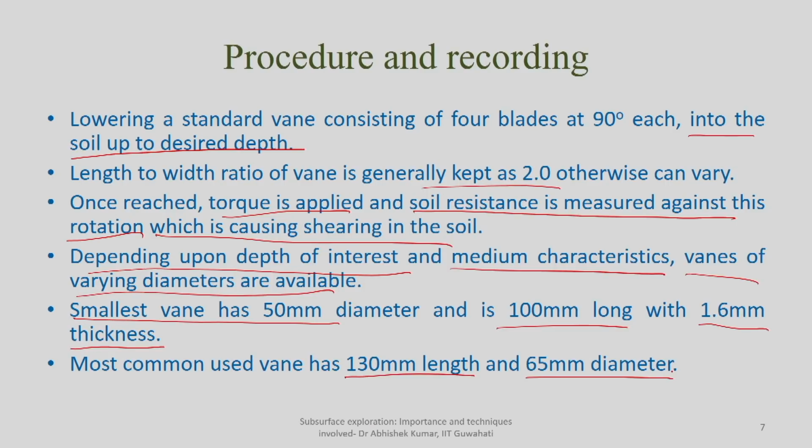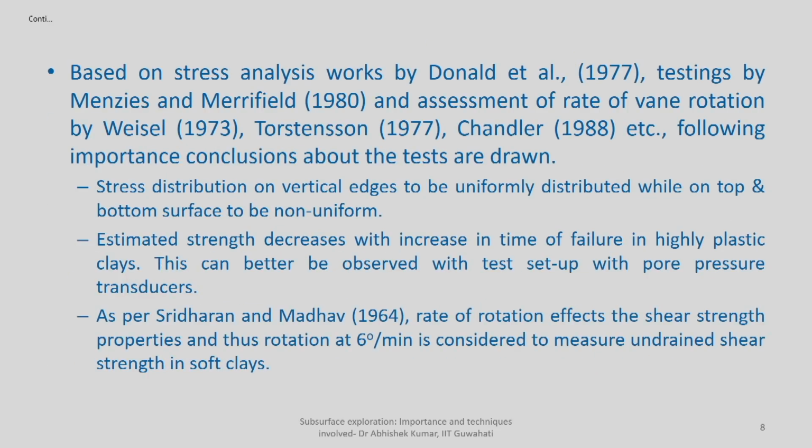The most common is a 130 mm length and 65 mm diameter vane. As I mentioned, after the Kempton and Clarkson work, a lot of work has been done towards standardization and stress analysis also. Some of the work was done by Donald in 1977, Menzies and Merrifield in 1980 on rotation, and assessment of the rate of rotation by Wiesel, Torstenson and Schindlers in 1988.